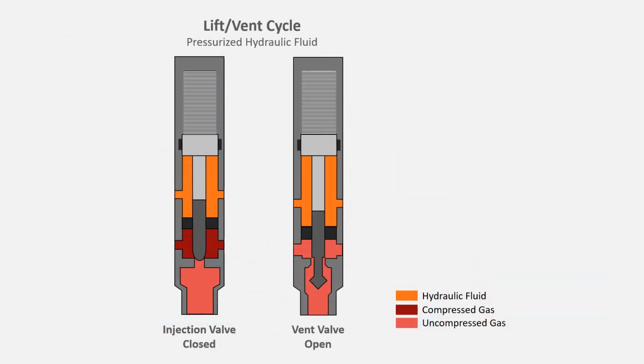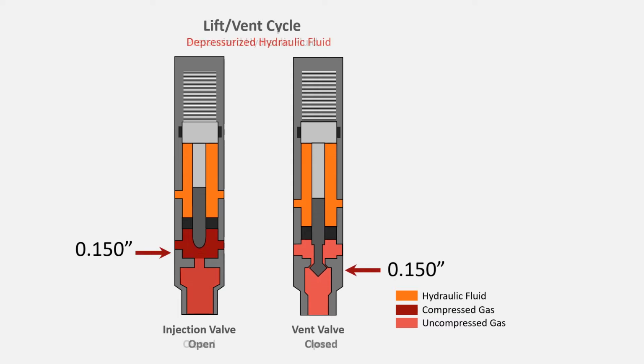Gas pump systems do not use rods or moving reciprocating pumps. In fact, the only moving parts are the balls in the standing valves and the pins in the two downhole valves, and they only move 150 thousandths of an inch.